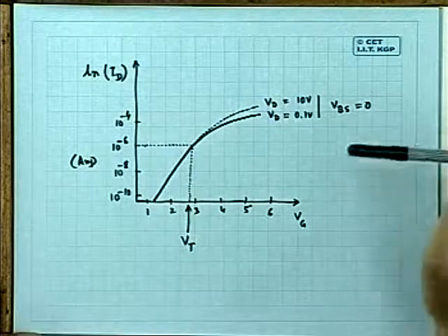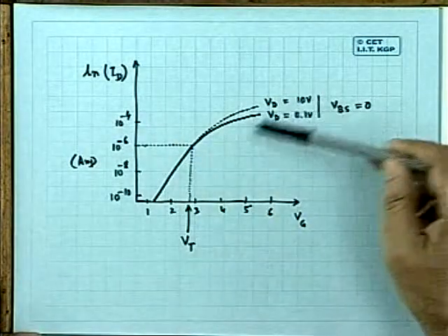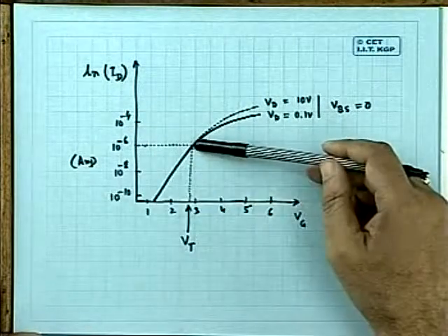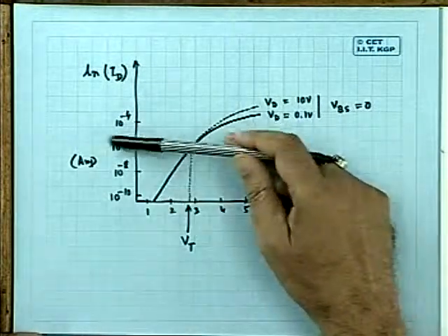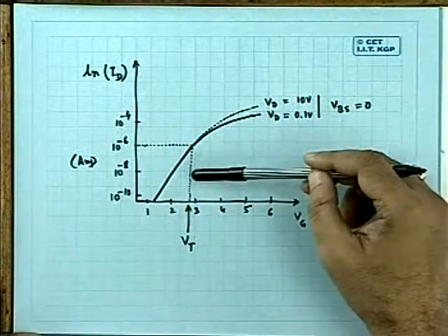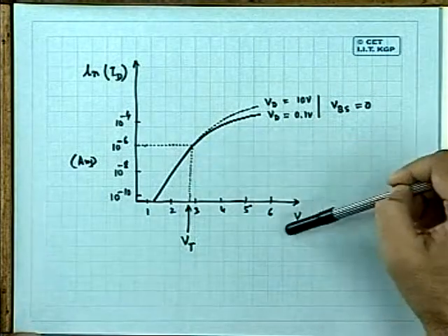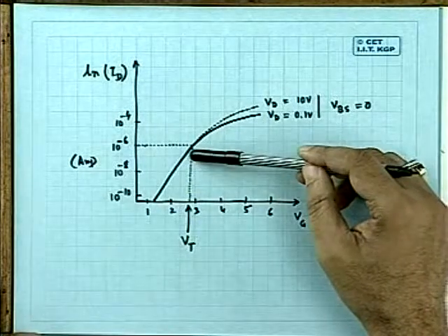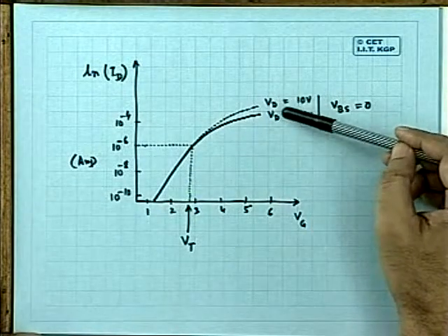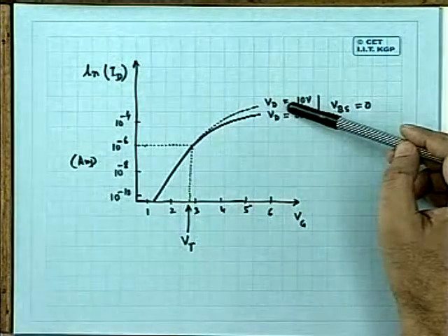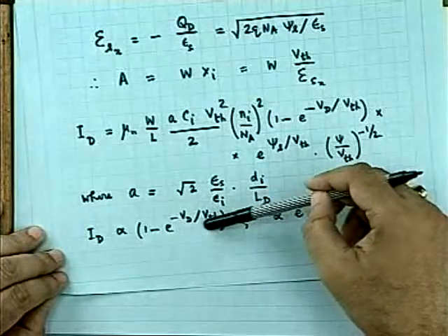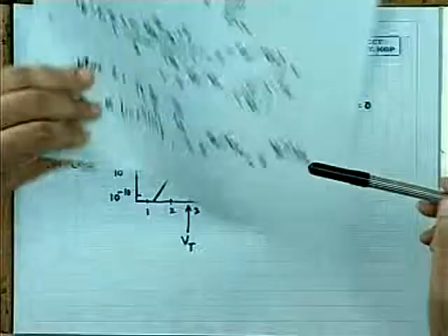You see that in the logarithmic scale, semi-log, the behavior is almost a straight line behavior, linear rise in the semi-log, that means the exponential increase of ID with Vg for small values of gate bias, but as gradually it tends to saturate, and for different values of Vd the curves do not vary much simply because of this term. Okay?